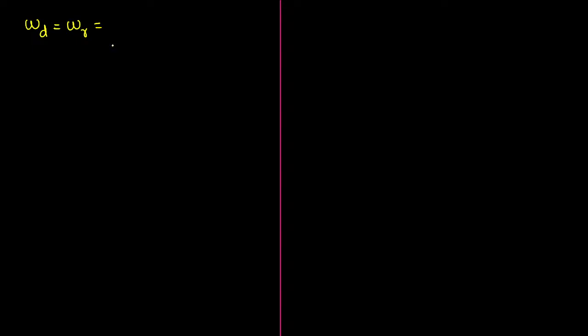There, what we will do is connect the RLC load on our load side and calculate this frequency. This is called the ringing frequency. In power electronics we are calling it as ringing frequency. You name it according to the application. That's all.